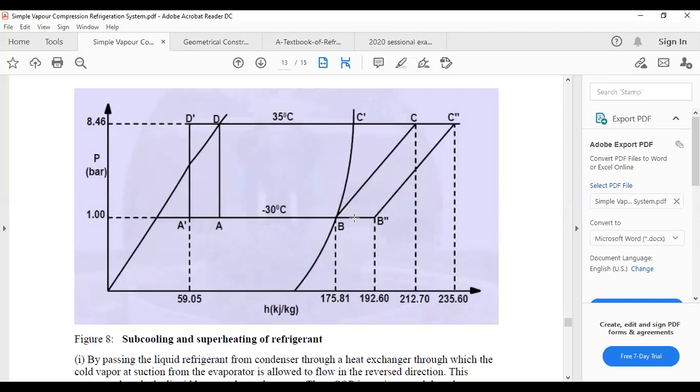This happens even when some people have a tendency of not understanding how a fridge works. They just pick up food from the stove or from the brazier and take it straight into the fridge. Because of that high intense heat, the refrigerant will be superheated, meaning you leave the evaporator superheated. So that will make the compressor overwork.